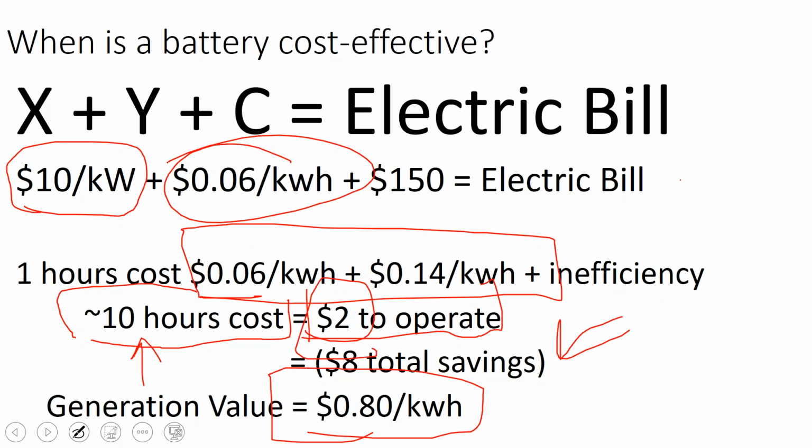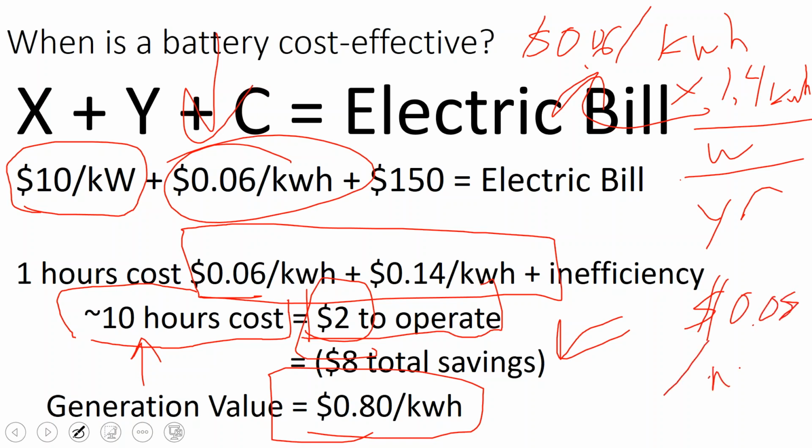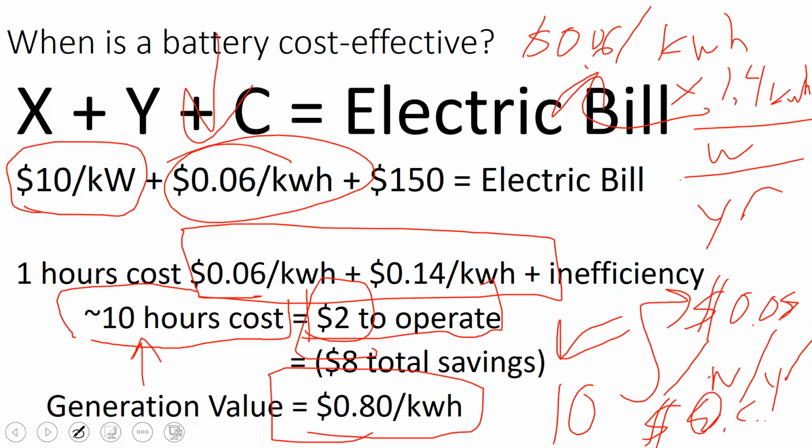And by itself, for a commercial client that's doing a 100 or 200 kilowatt commercial rooftop array, if they generate at 6 cents and they only get that commercial payback, well, what's that going to be? We've learned in our solar class, you should be able to calculate this by now. If we have 6 cents a kilowatt hour, and then we multiply it by, let's just say our solar array produces 1.4 kilowatt hours per watt per year, 1.4 times 6, what that means is we're going to have about 8 cents a watt a year in payback. And so if I have a 10-year payback on my commercial array at that point, I need my total project cost to be around 80 cents a watt.